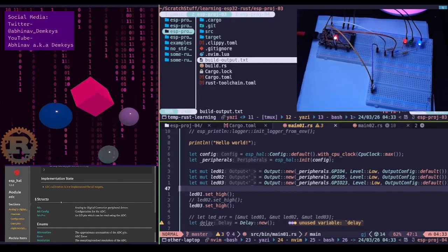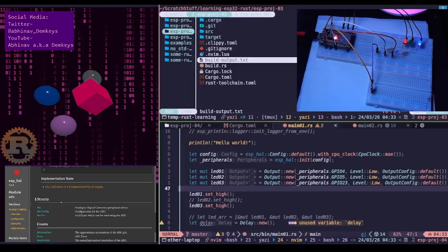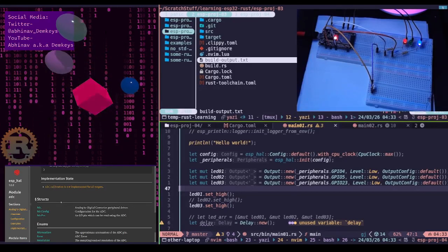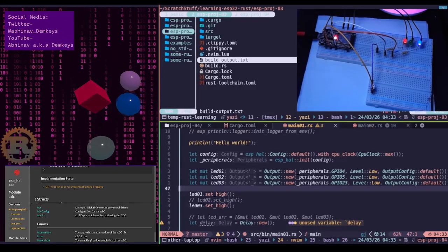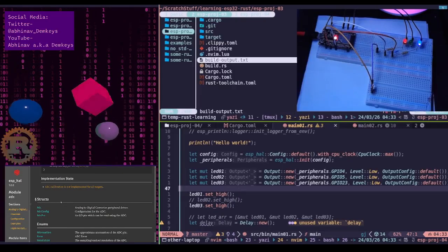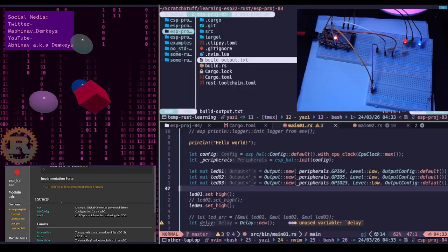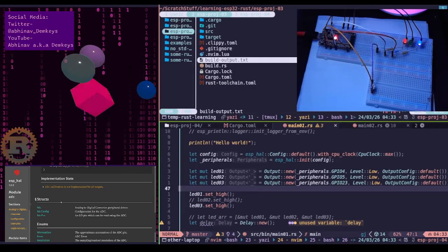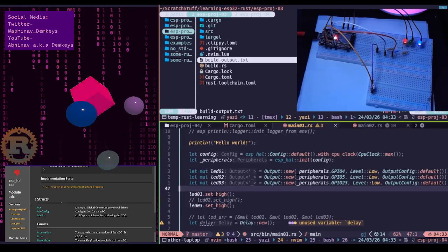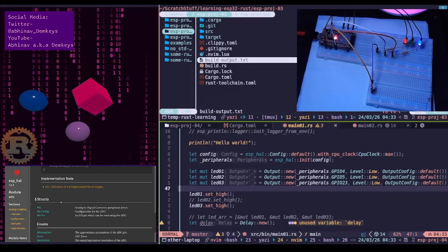Turned to one side, the wiper is physically touching pin 1. There is zero resistance between the input and the wiper. So the output there would be 3.3 volts. And if it's turned all the way to the other side, the wiper is touching pin 3.